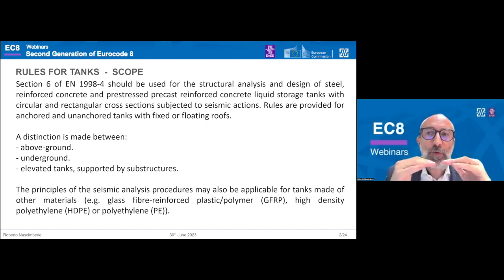Then subdivision due to constraint and material. The rule can be applied to steel, welded and bolted, reinforced concrete, and pre-stress precast reinforced concrete material. It's important also to highlight that we extended also to other materials. We wrote glass fiber reinforced plastic or polyethylene, or high density polyethylene. There's a but: only the principle of the seismic analysis procedure may also be applicable.